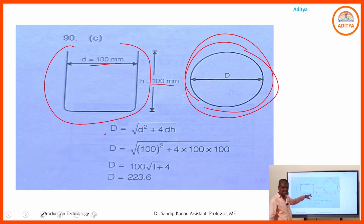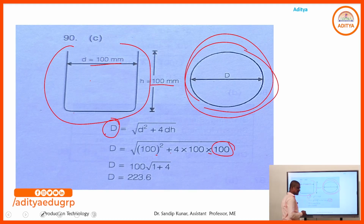Using that formula, finally we have got the blank diameter capital D equals root over d square plus 4dh, where d is the diameter of the produced cup, 100 millimeter, and h is also 100 millimeter. Using the calculation, finally we have got 223.6 millimeter.